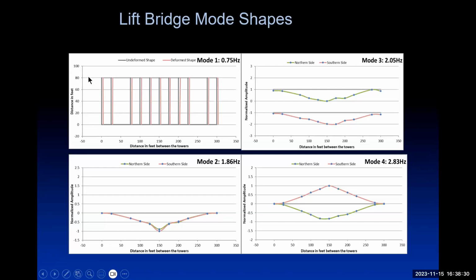The thing was that just before this was a toll bay. And if you imagine you pull up at a toll bay, and what do you do? You accelerate away. Even if it's gentle acceleration, you are creating a force. So this type of mode was actually excited by people coming away from a toll booth.